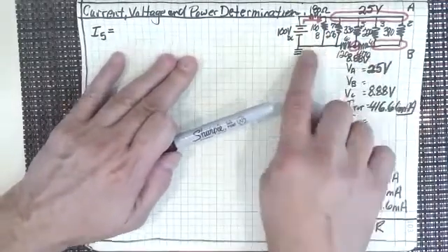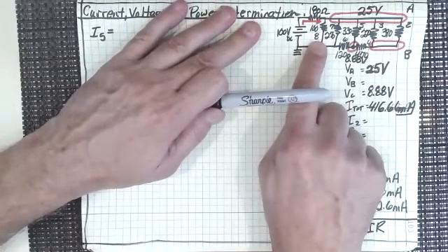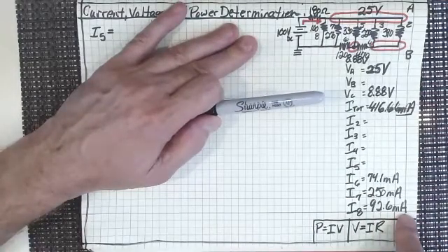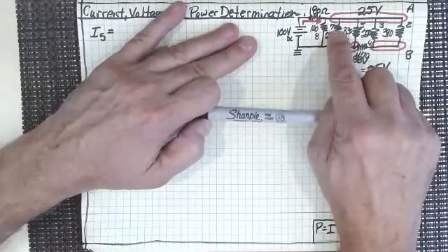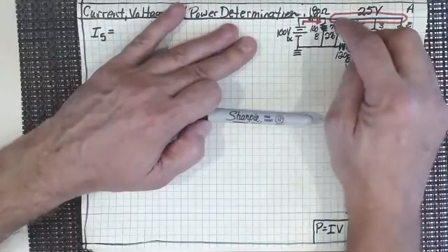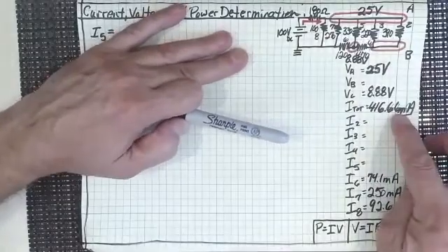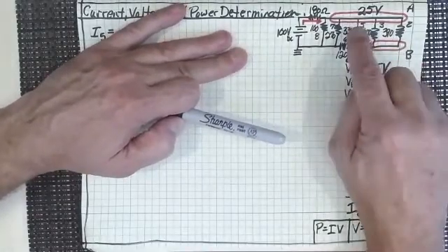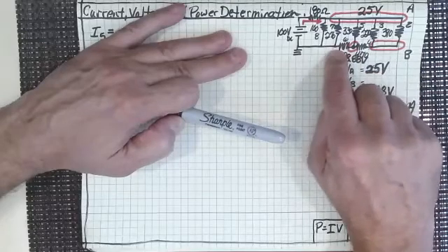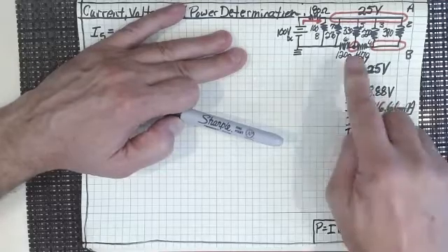So let's look at that. We now know that current in that first one at that 100 ohm resistor that's going to be coming out, that's I sub 8, is 92.6 milliamps. And we know that the current through I7 is 250 milliamps. And what that told us was, okay, that current is already coming out of the total 416.66. We knew that the current that came back through here had to all sum up to the total current, 416.66 milliamps, right at that point.